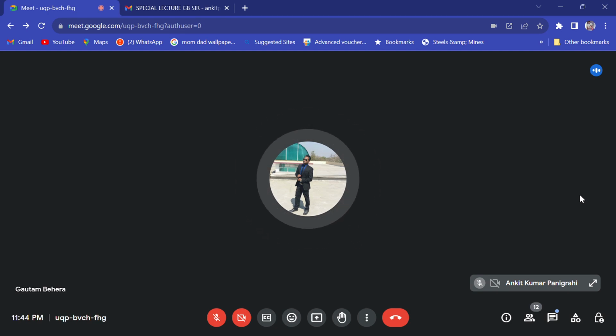You want to send oxygen to every part, so it will be faster, right? But when you're doing top blowing, the top part will get agitated more, but the bottom part of the reactor will not be agitated as much. So there will always be a difference in oxygen and in the impurities level. That's why bottom blowing is more advantageous.